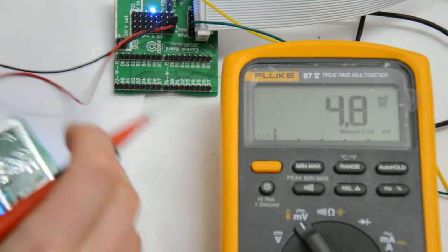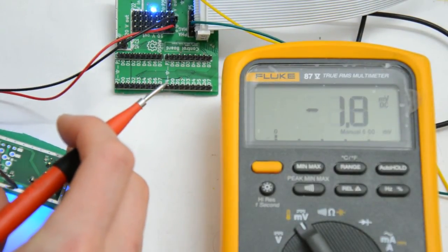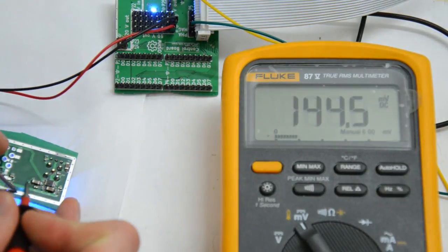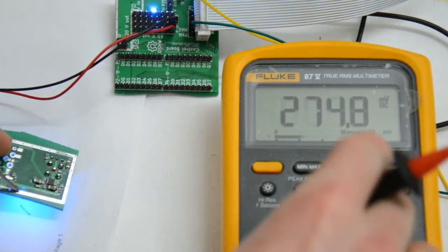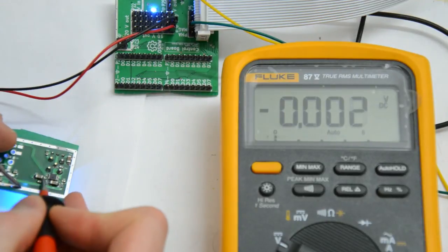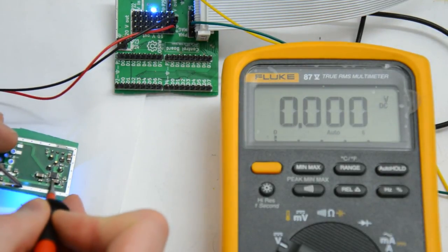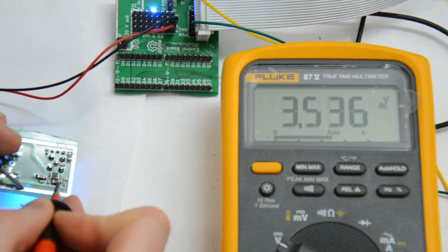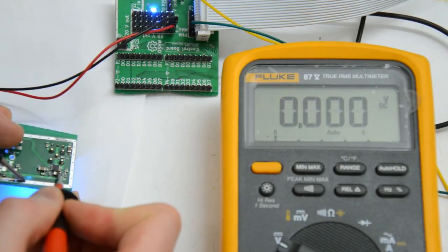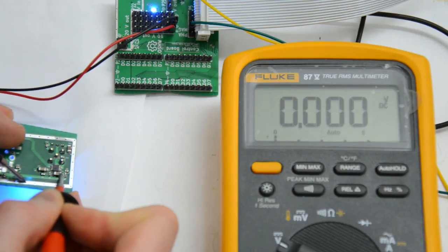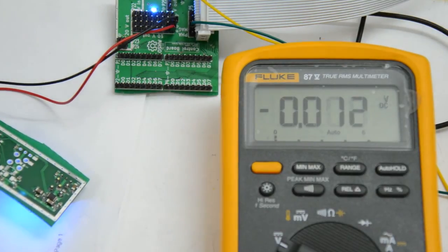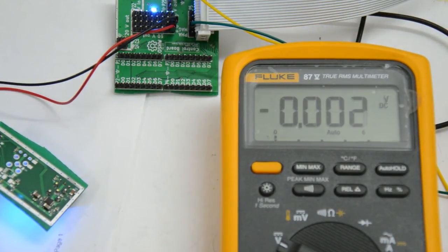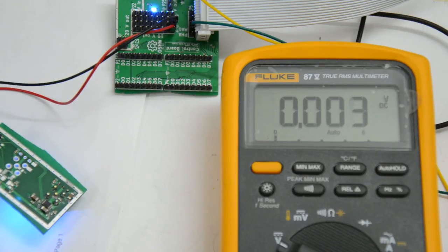In fact, I could also measure a bit. I measured the 5 volts from the regulator already, but I can also check whether I get these. That's the ground side of the capacitor, and I've got this on millivolts, so let's turn this back. So I'm just checking now whether I've got my 5 volts not just at the output of the regulator, but also on these capacitors, and that is the case. So great. This seems to work fine so far, apart from the wrong measurement. I'm not too concerned about it, although I will run a few more tests on the computer.